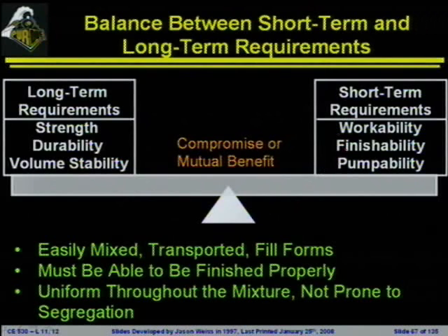So workability, finishability, pumpability, flowability, for all of these things, we would say the water content could be fairly high, and it makes all of those aspects of the concrete a little bit easier. On the other hand, all of the long-term properties of concrete, whether it's strength, durability, shrinkage, volume stability, want the water content to be a lot lower.